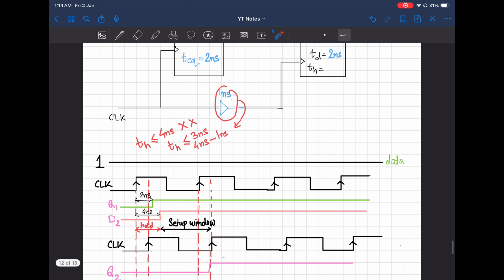So that's why we talk about the hold constraint. Mostly we talk about the hold constraint when we do clock tree synthesis. When we do logical STA, we rarely talk about the hold time constraint, but at clock tree synthesis and sign-off stages, that time we talk about the hold time constraint.